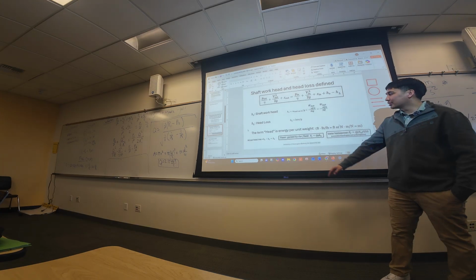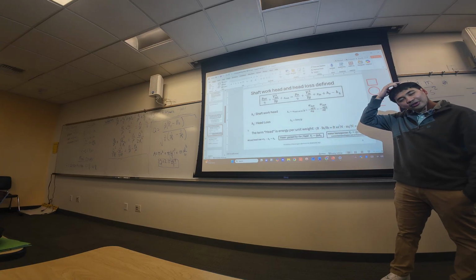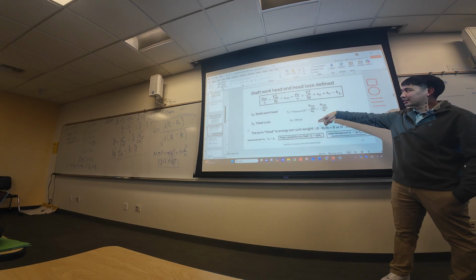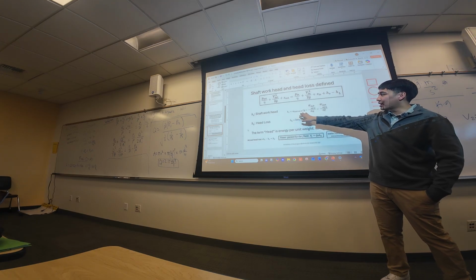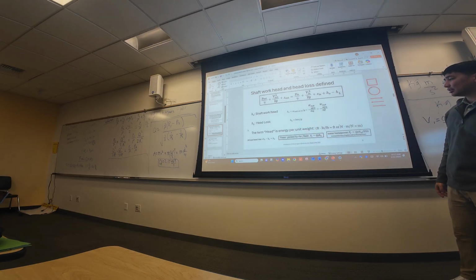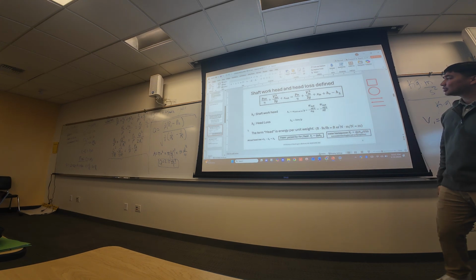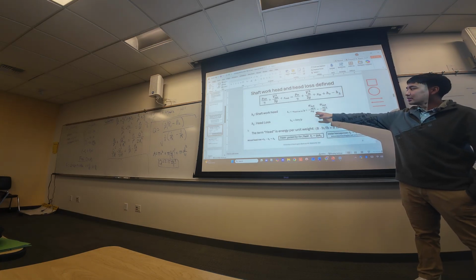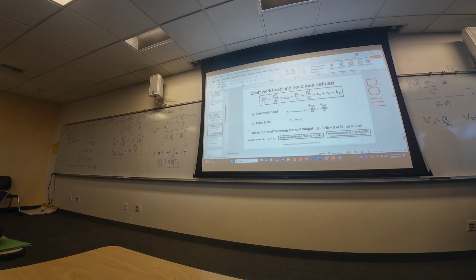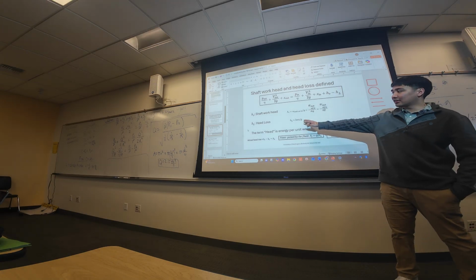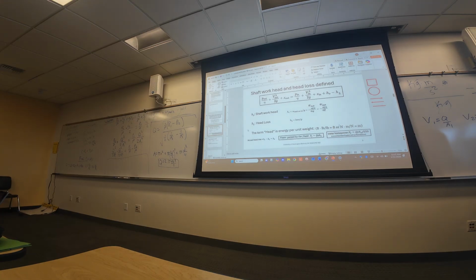And I found some more derivations if you need these terms. You'll see in your homework that you'll get HS and HL from your equation here. Right, so shaft work head is just your net shaft work in divided by gravity. And that makes sense because, right, you have these units of head, which is just meters. Okay, work shaft in divided by mass flow rate times gravity. You can sub in your Q. That's the shaft work head there. Head loss, it's that loss term, which we defined earlier, right, with that whole internal energy U hat thing, divided by gravity.